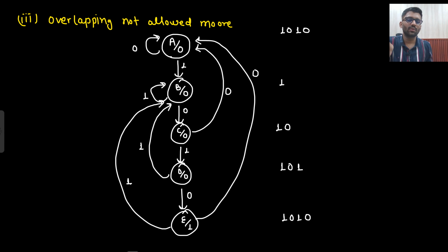Now your task is to design the same, but for the case of overlapping allowed. Overlapping allowed, Mealy, you need to detect 1010. Pause the video, do it on your own. Okay, so let's start doing it.